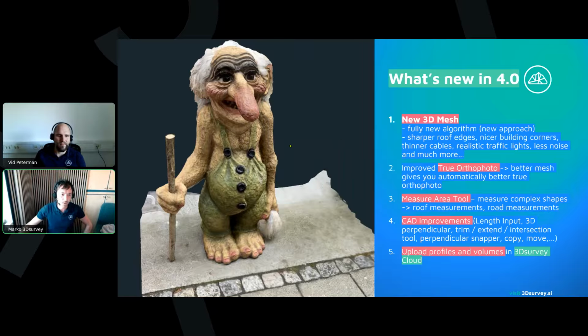I need orthophotos for my customer with the volume calculation. I will have to generate DSM mesh and a full 3D mesh too. This is what we recommend. So when you start reconstruction, just leave all the checkboxes on. After the reconstruction is complete, you will already have an orthophoto, full 3D mesh and a point cloud.